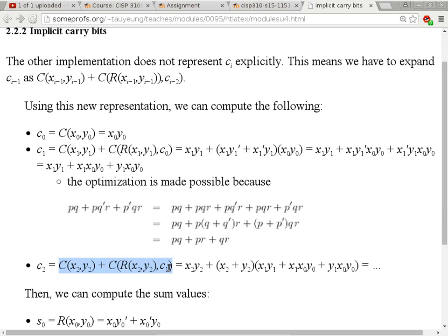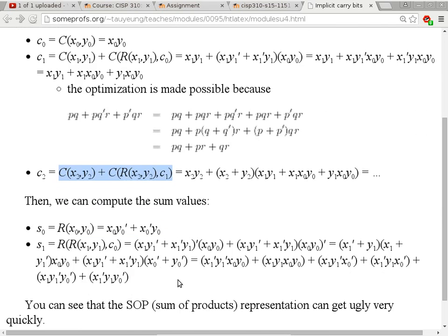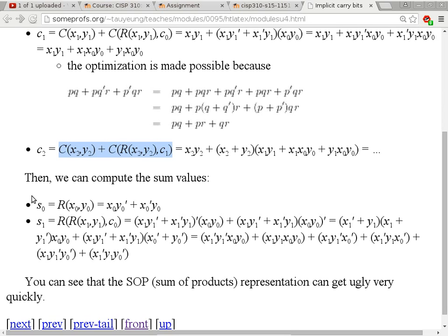And this is just the carry. What about the sum, right? So the sum is nastier. This is no surprise, right? The sum of bit 0, hey, we know how to do that one. Exclusive OR is like that. Okay, cool, we know how to do that. This is the sum of bit 1. Now the sum of bit 1 in this picture is H, okay? So we know how to come up with that one too. It is the result of adding the 2 bit ones from the numbers themselves, and the carry from the less significant bit, or the least significant bit in this case.